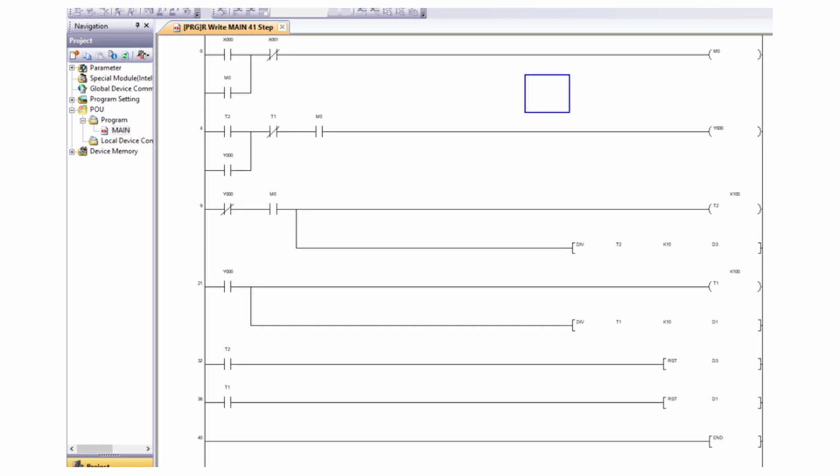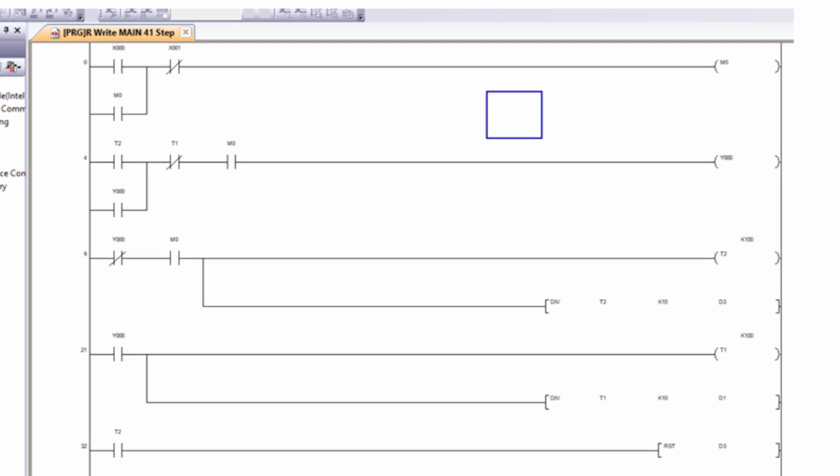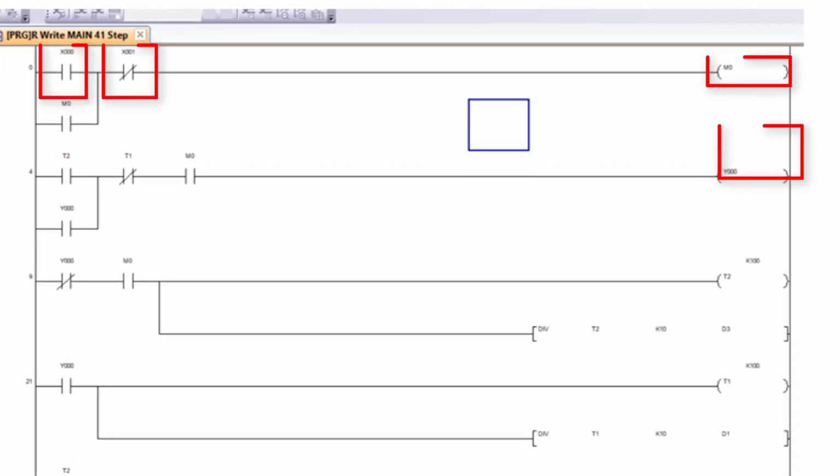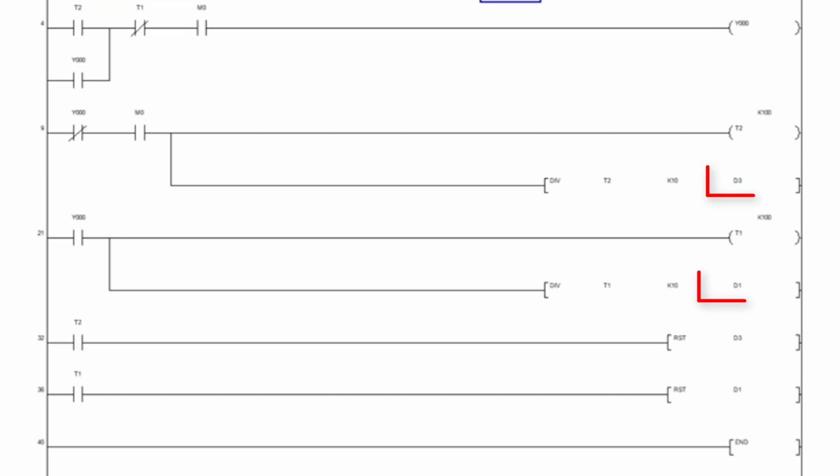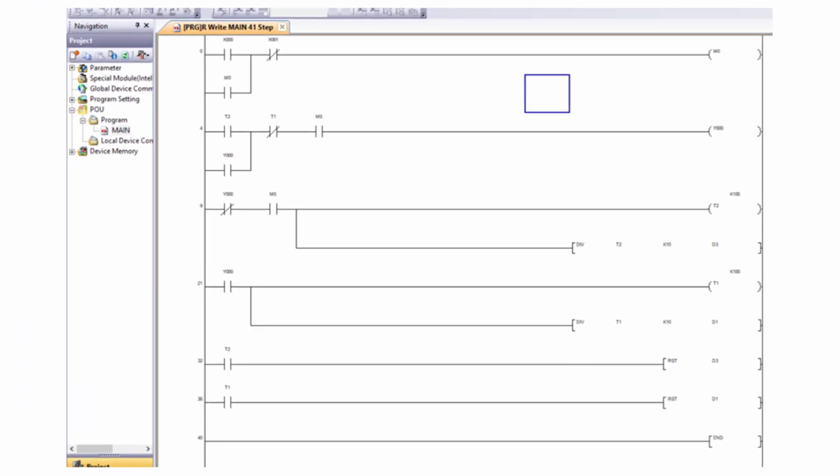So, to get the desired motor operation, first we have to create the PLC ladder program using the Mitsubishi GX Works2 programming software and download this program to the Mitsubishi PLC. Take a look at the PLC ladder diagram where digital and analog data have been defined to send to the WinCC SCADA system. The PLC ladder diagram has already been created and downloaded to the PLC. As our main topic of this video is the Mitsubishi OPC Server configuration and SCADA project creation with the WinCC SCADA software, the PLC ladder diagram creation and downloading procedure have been skipped in this video.